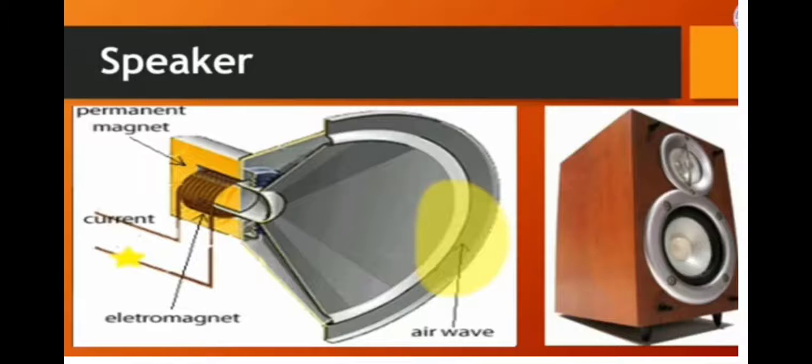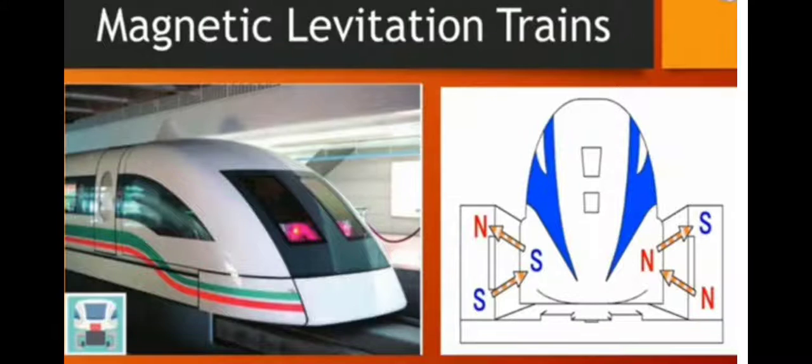As pulses of electricity pass through the coil of the electromagnet, the direction of its magnetic field is rapidly changed. This means that it is in turn attracted to and repelled from the permanent magnet, vibrating back and forth. The electromagnet is attached to a cone made of flexible material such as paper or plastic, which amplifies these vibrations, pumping sound waves into the surrounding air towards our ears.